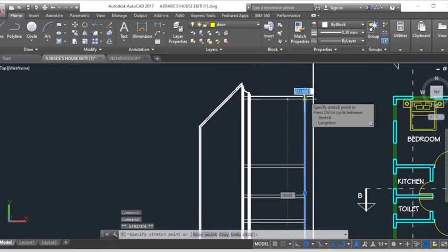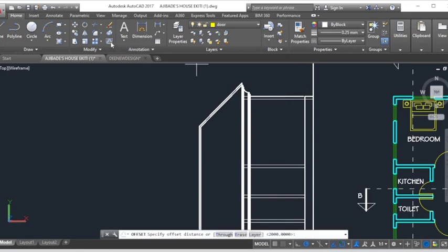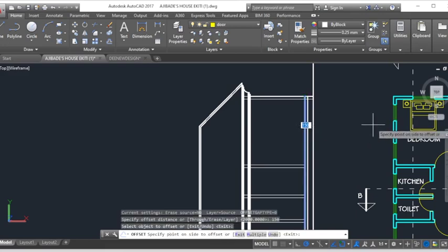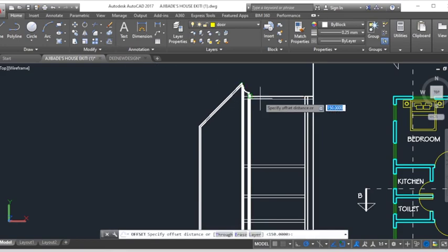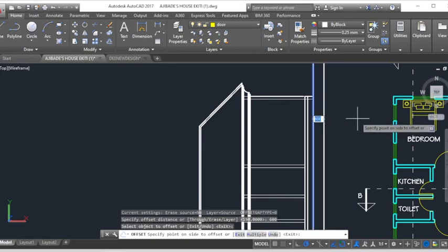From the belt design it's cutting across, and I don't want that. So our German floor is 150. So click on offset, then input 150, then enter. I'll just click on this line, then I'll drag my 150. That being done, I'll leave that. Then I want to specify my foundation going into the floor. So offset, let's see, 600, enter. So I'll just take 600 from here downwards, right?